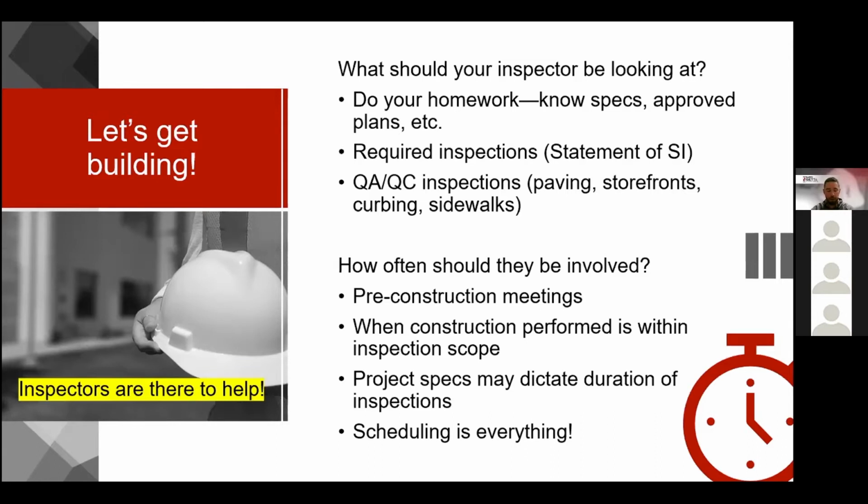And again, I reiterated this, but project specs may dictate the duration of inspections. And scheduling is really everything. We don't want to install something and have it buried or drywalled without an inspection because it really makes more work for everyone. We don't want to miss out on concrete testing and then all of a sudden we want to put something on it, or it just doesn't work out. So the scheduling is very, very important.